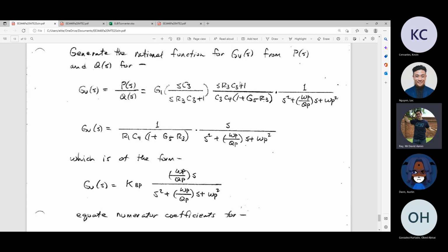So to figure out what kind of order it is, if I have an S cubed in the numerator and an S to the fourth power in the denominator, then that's a first order system, because the S cubed in the numerator, no matter how they're multiplied out, cancels with the bottom one, kind of making 1 over S plus something. That's just a way to think about it whenever you see this.